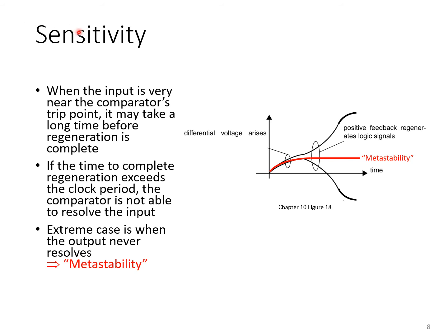Now, clearly the sensitivity of the latch depends on how long you have to wait. Even very, very small differential inputs of a microvolt or a nanovolt, especially in simulation with no noise, will eventually resolve if you wait long enough. If the latch is perfectly reset and you wait long enough, eventually the positive feedback will take over.